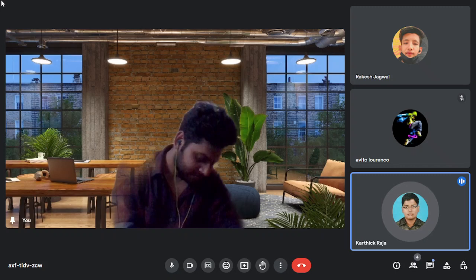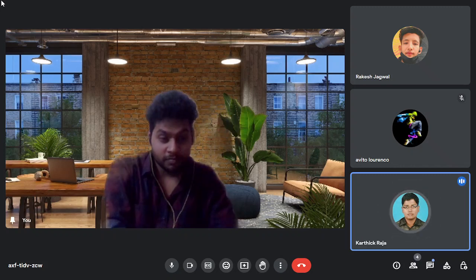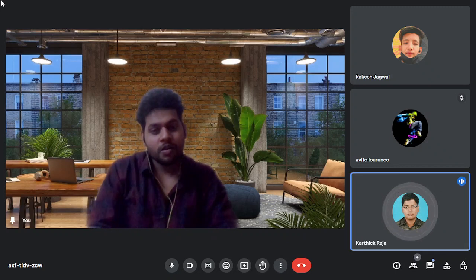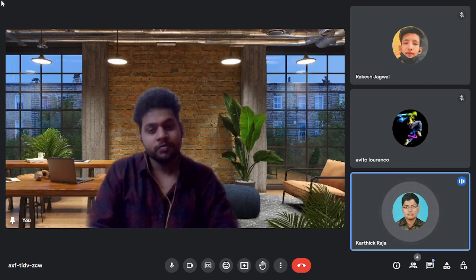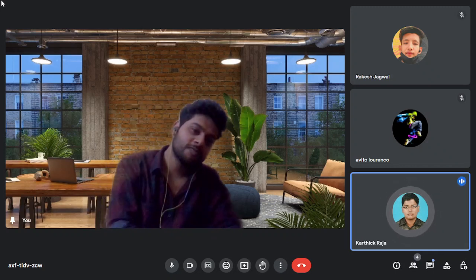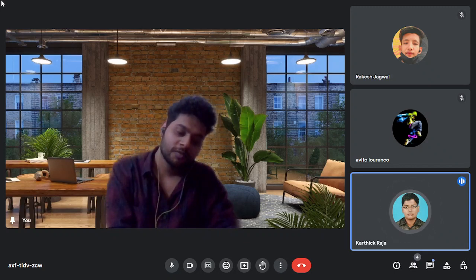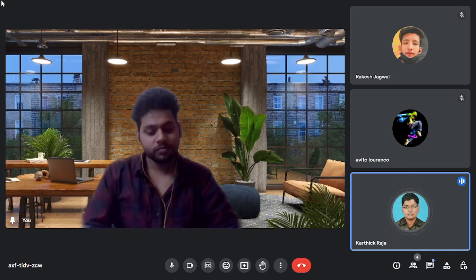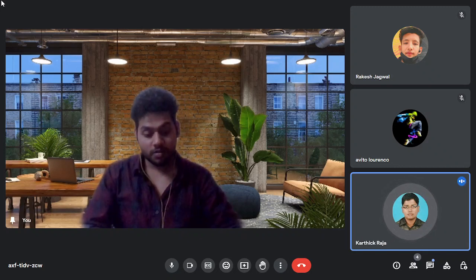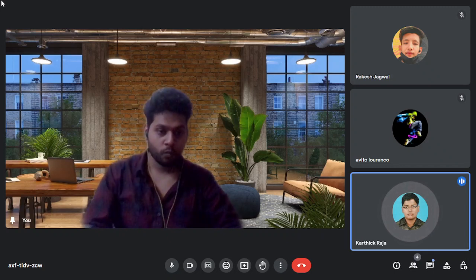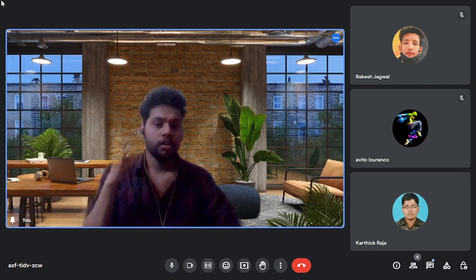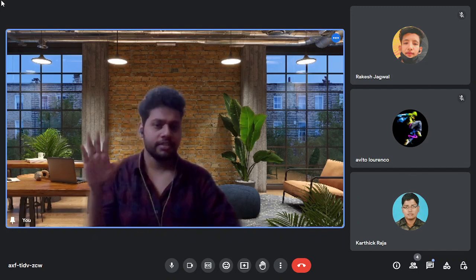There they have a resonance. If the frequency of the rotating shaft is equal to the resonance speed, then we have this critical, and that's called the critical speed. At that time, the metal can easily break or it causes serious damage. So in ships and everywhere, we won't like to reach a critical speed. Critical speed is not the highest speed.